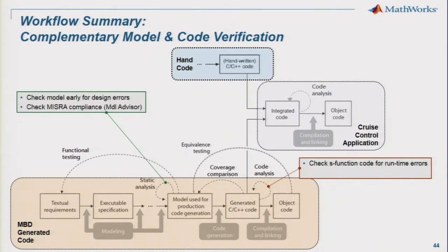And then the Misra part, key thing here is we did some stuff with Model Advisor. We checked as much as we could in the model to kind of ensure that we'd have minimal rework. Again, not a complete guarantee. So it's kind of a handshaking between the Model Advisor checks and what we did with Polyspace for the final checks. That's correct. That will kind of guarantee the Misra compliance. And again, we did that before functional, so we knew the code I delivered to you was going to be Misra compliant.